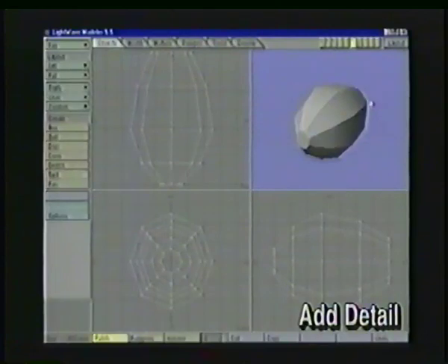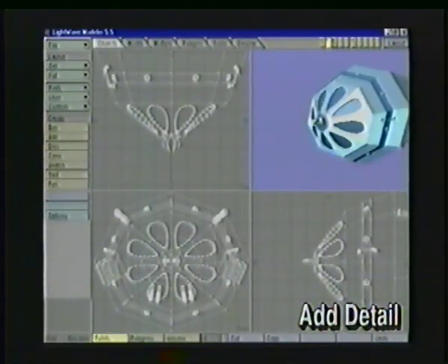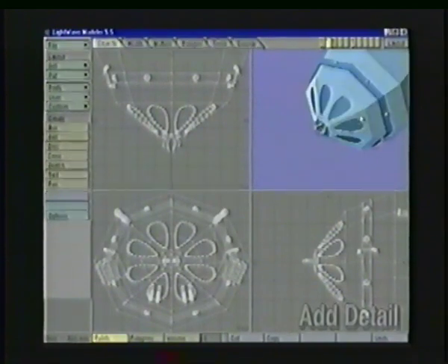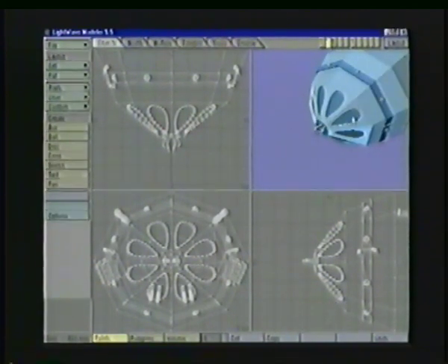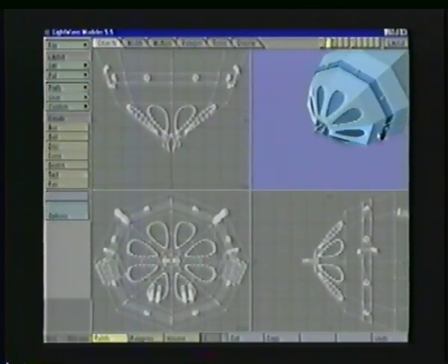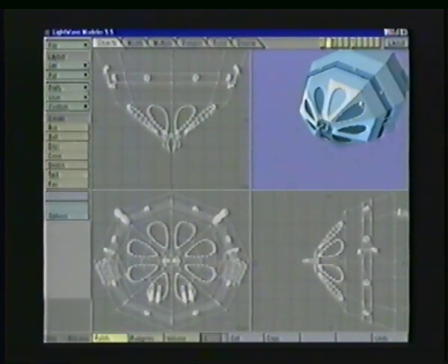I'm going to go back and look at my original object in case you've forgotten what it looked like. The tail end has these fancy little ornate indentations. This could be accomplished through a Boolean subtract operation. However, I have a much easier way of doing this. Now you notice the shape is sort of a squished oval shape, so once again we're going to use the disk tool and the taper tool. It's going to be quite simple.